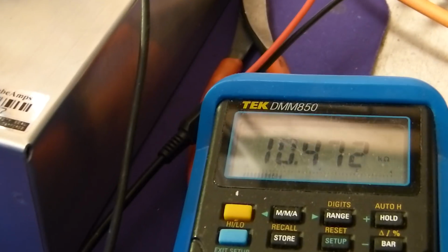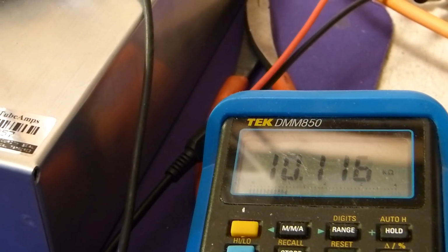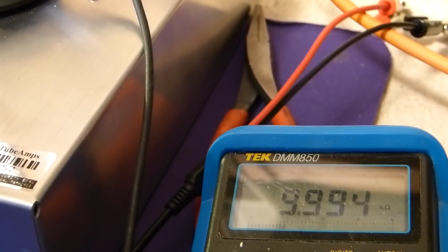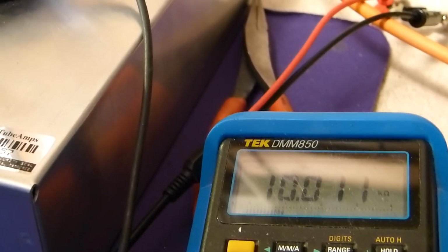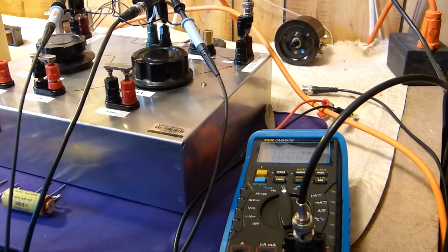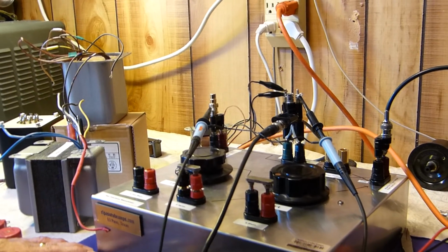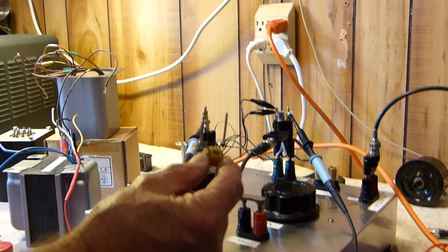So you can use potentiometers for it if you want to. And you can dial these multi-turn pots into exactly what you want. Don't be nuts about it. 10,008 ohms, 10,005 ohms. Give it time to settle down, and then you can plug those numbers in too. You can use that as a 10,000 ohm resistor, and you'll get exactly the same answer as you do by using this fixed resistor.